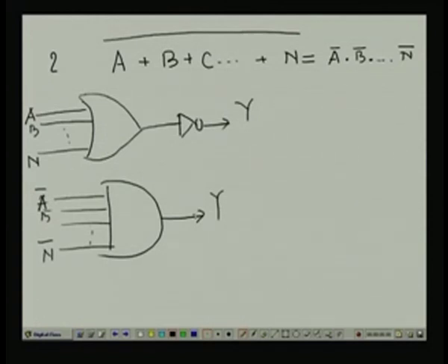Now, the first one we have seen that how from AND gate the OR gate can be derived, here from the OR gate how AND gate can be derived. So, mainly that if we interchange the plus by dots and each uncomplemented variable be complemented, or that non inverted elements are inverted, or vice versa, then it will give the same results.